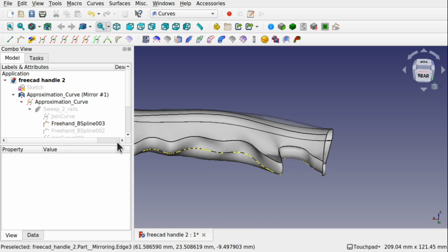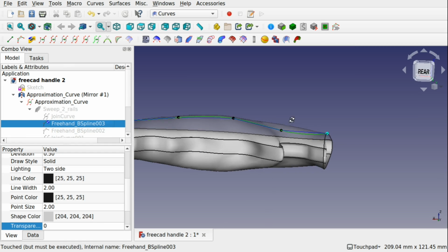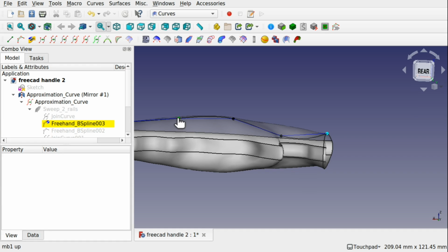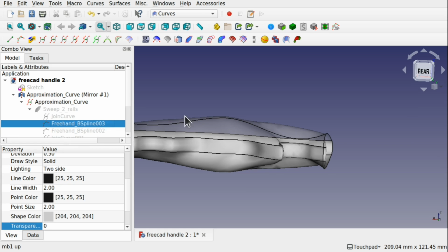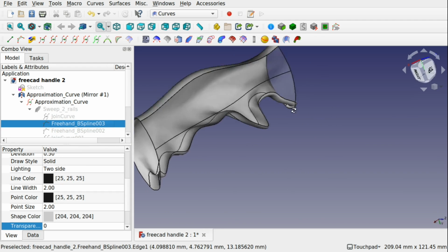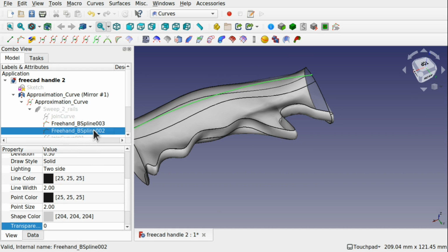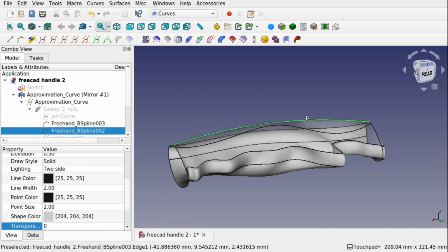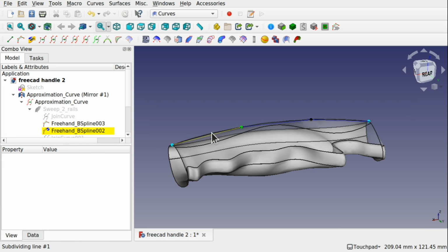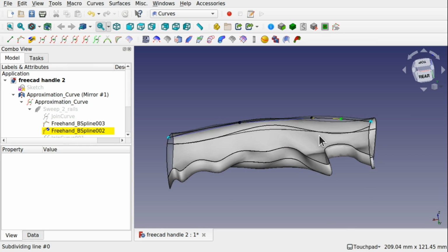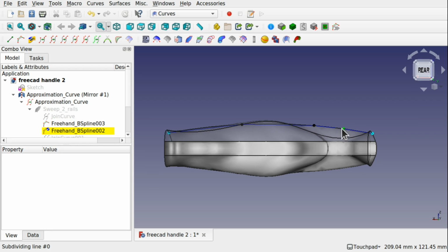So now when I come in that b-spline and change the curvature, let's go a bit more, and also let's control that belly there as well. Double click. Then we can see how that's being curved into shape. Let's do the other one. Bring the other one back. Double click, add a few more control points, and one up here. Click on rear, and now I can see inside as I dip this into there.